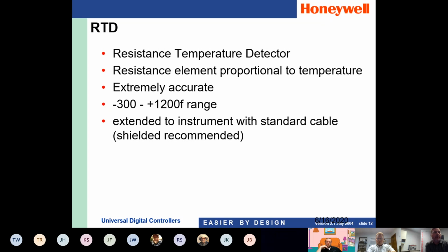So when we do these type of calibrations, we usually have a handheld calibrator where we can dial in the resistance, or a decade box, which we used to use way back when to calibrate these type of systems as well. But typically you'll either see a 2-wire, a 3-wire for long distances with the lead length, or a 4-wire in some cases for these RTDs.